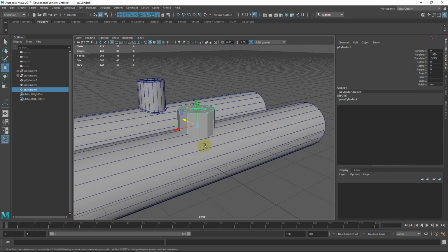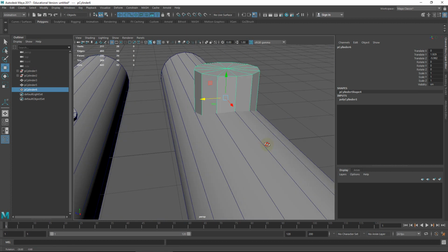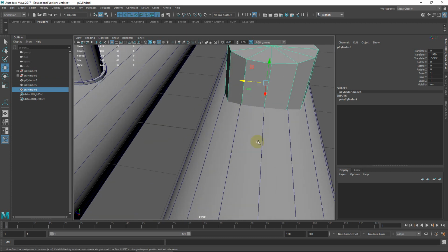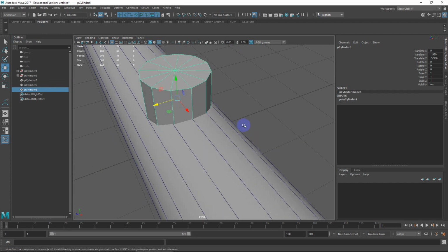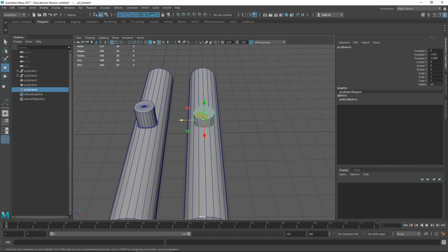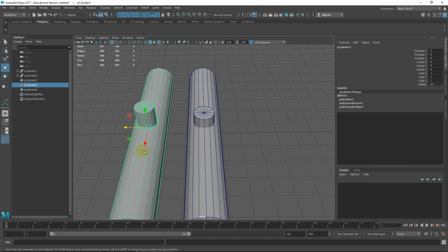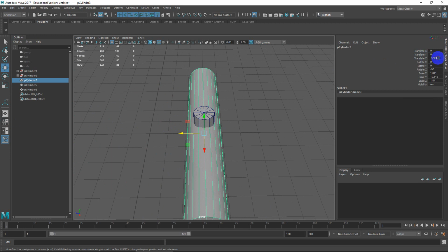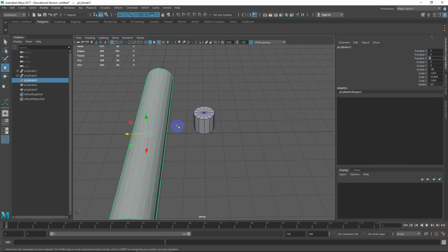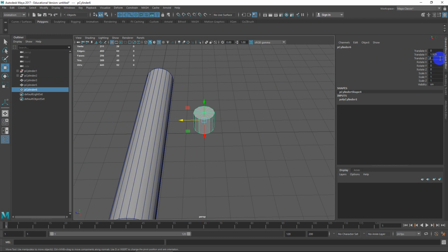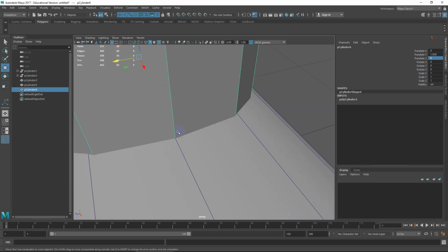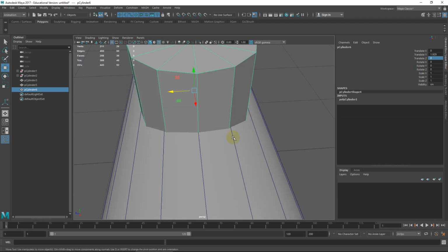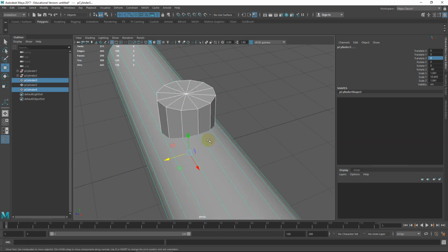Now, you may wonder, why does this matter? I'll show you in a second. I'm going to grab both of these. Actually, I'm going to move this off. When I'm modeling, I usually like to be at the center of the world. So I'll hit 0 on the Z-axis, and I'll hit 0 on this. So I know these two pieces are dead center, lined up perfectly across that center line. These edges are matching up pretty closely.